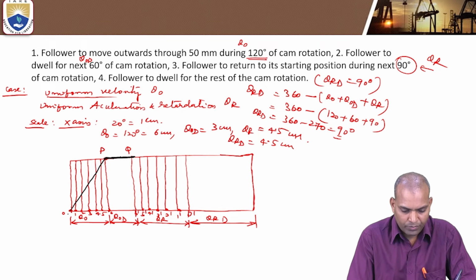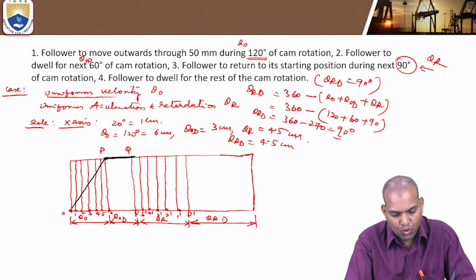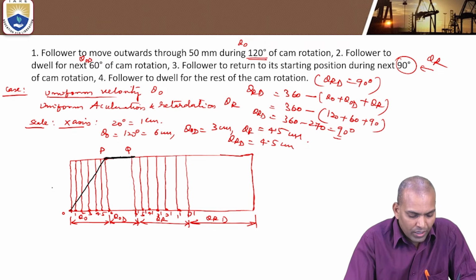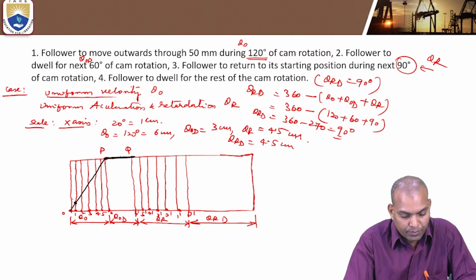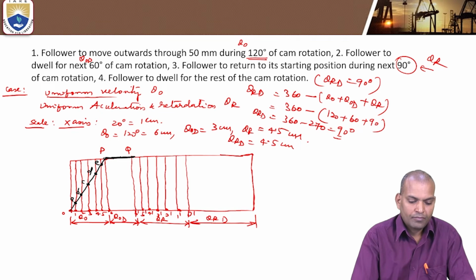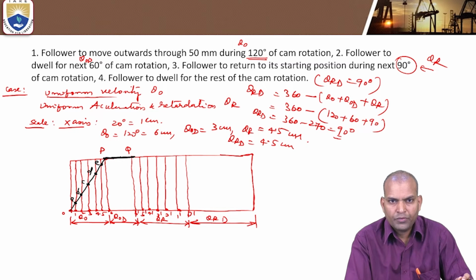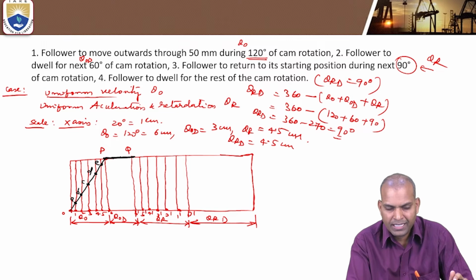When the outstroke is uniform velocity, the displacement curve for the outstroke is OP. The vertical and inclined lines intersect at a point A. Mark the other points as B, C, D, E, and P. So the displacement during the outstroke of the follower is the vertical rise.